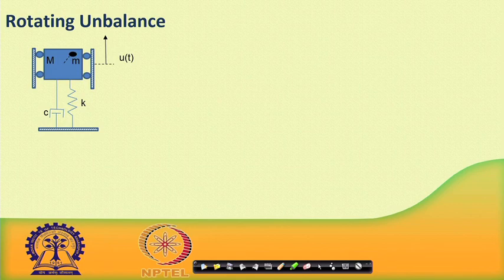Now, since it is rotating, it is of course going to experience a centripetal force, which is nothing but the rotary inertial force that the rotating device is experiencing. When we have a nicely balanced rotating device, this inertial force cancels out, and the resultant force in the horizontal or vertical direction is zero, and therefore the resultant vibration because of the rotation of this device is 0.